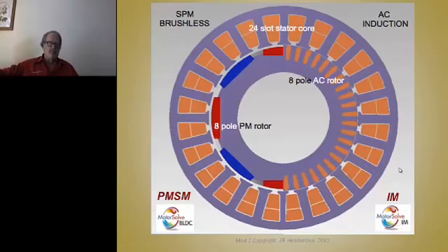I just wanted to make that point to give you a feel for the difference between slip or imaginary moving poles, because we're going to find out later that slippage, by the way, varies with torque, the load on the machine. And that's why the induction machine has such a poor torque speed curve, not a very useful one, when it's driven by constant frequency and voltage without being able to control the magnetizing current separately. We're going to study the magic of that later. So that concludes this lecture.